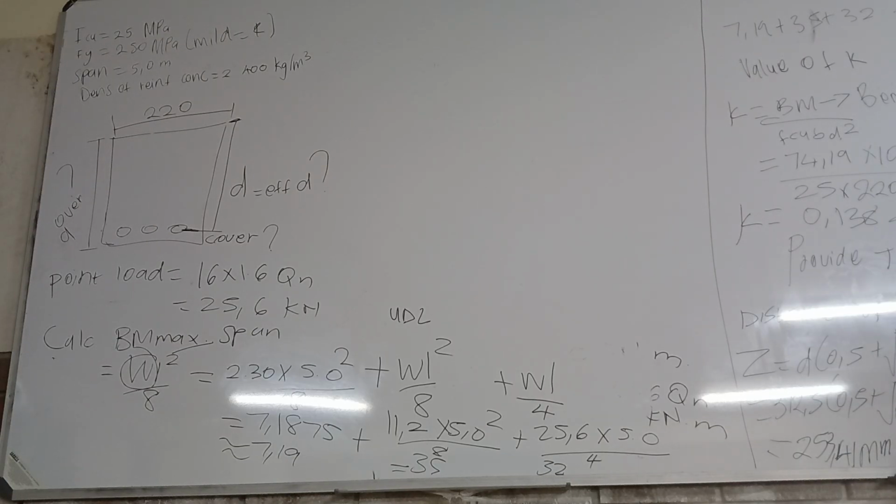So we are not done. The formula is also less than or equal to 0.95 times 312.5, which gives 296.88. So now we have two values of Z. For the final answer we need to choose the least one. Which one is the least? 253. Therefore Z is equal to 253.41 millimeters, choosing the least one.